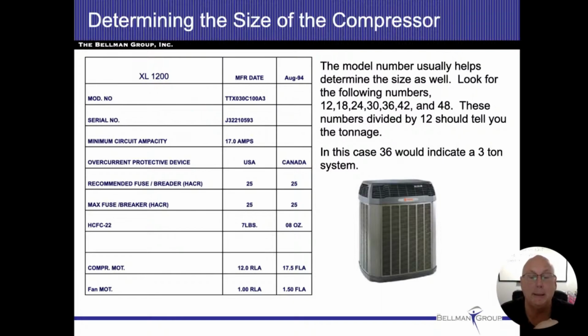All right. The next size larger wire is going to be a 12 gauge wire. That 12 gauge wire is good for 20 amps. Okay, 20 amps is more than what this thing needs for its minimum amp. So I could feed this air compressor cabinet unit with a 12 gauge wire.